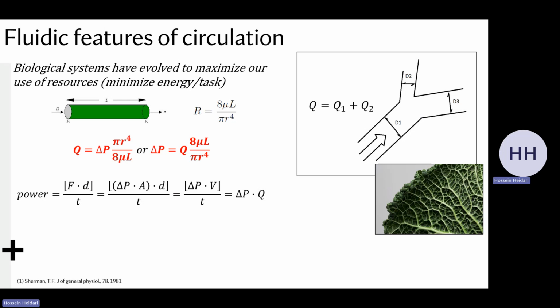So you're basically having delta P times Q, which is the amount of power required to push this chunk of fluid through a pressure difference of delta P at a flow rate of Q. So basically, this is a key bit of the derivation. And then the second bit of the derivation, so now you can just substitute. You can put delta P as what you had there, and you arrive at this equation here. Substitution.